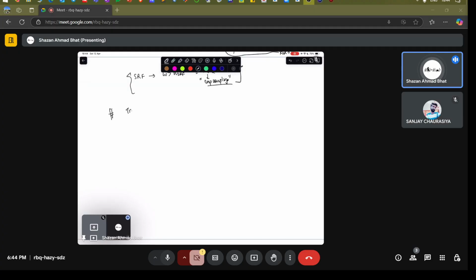And you know about transformers, they are basically implemented with these inductors. So you have something called mutual inductance and self-inductance. If you have two inductors lined like these, then you have the current flowing in these based upon the coupling of magnetic energy from one inductor to the other, based on the coefficient of mutual inductance. In microwave circuits, these are all fabricated at micro fabrication level. This is not like a huge transformer, like the one supplying power to us. These are micro fabricated in micrometer dimensions.